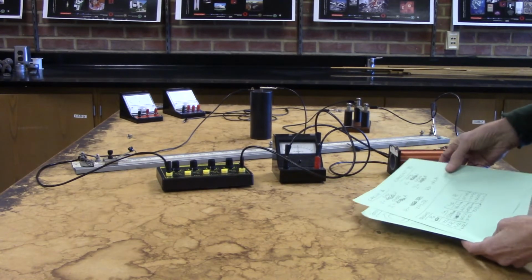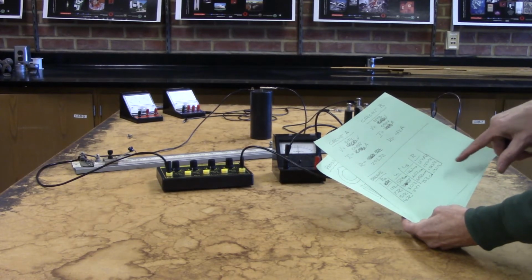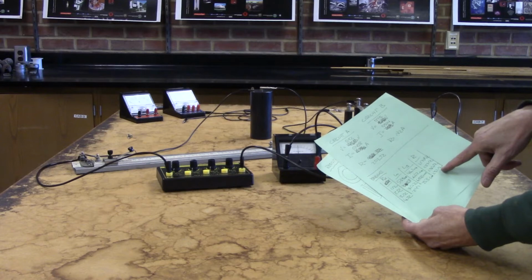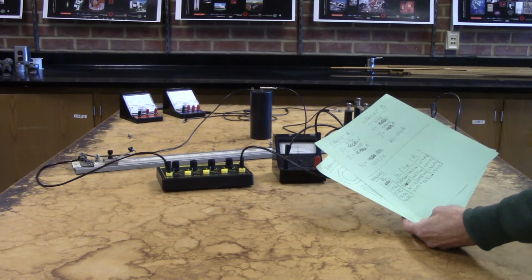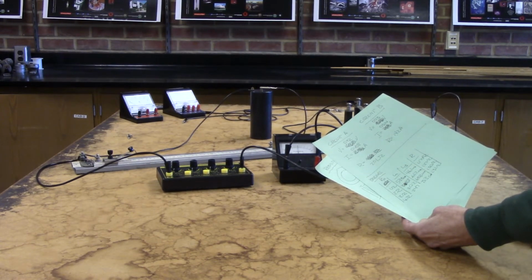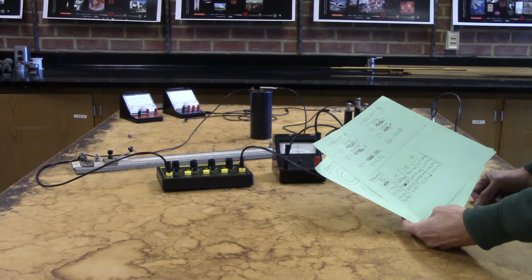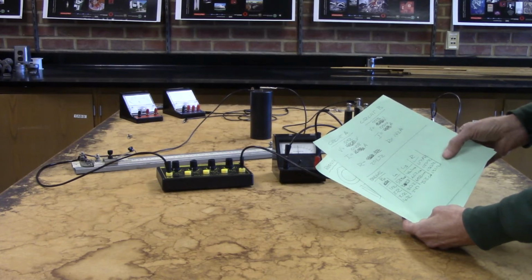Now my concern at this point is that circuit A and circuit B don't really match up very well with what I'm finding on the bridge circuit. So I'm going to go back and look at circuit A and circuit B again. I'm a little concerned about the voltmeter and the ammeters there, that they are not accurately calibrated. If I've got voltmeters and ammeters that are off, that's going to cause a problem for us. But the bridge method seems to show some real consistency here, so that's encouraging.